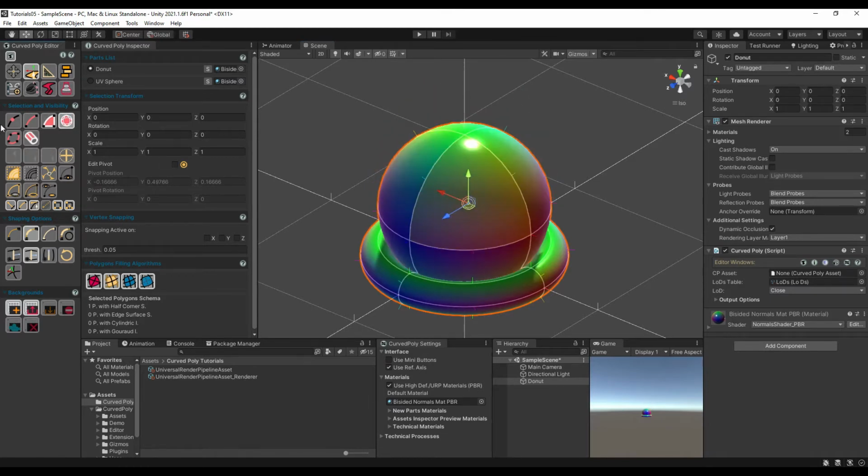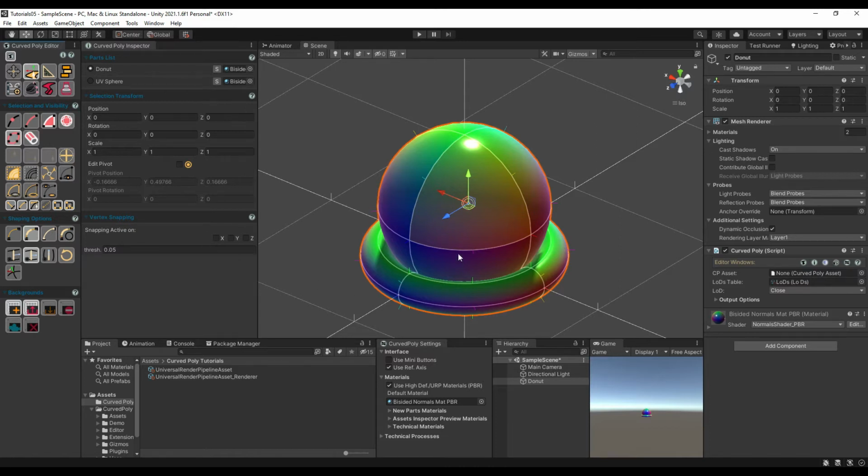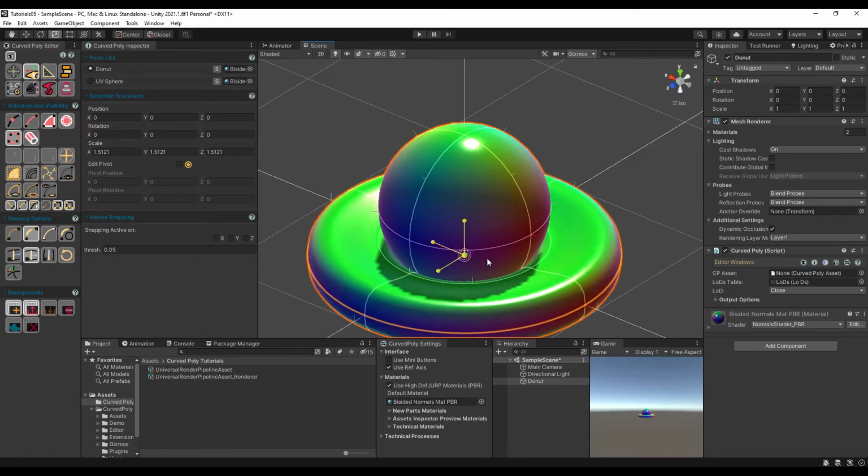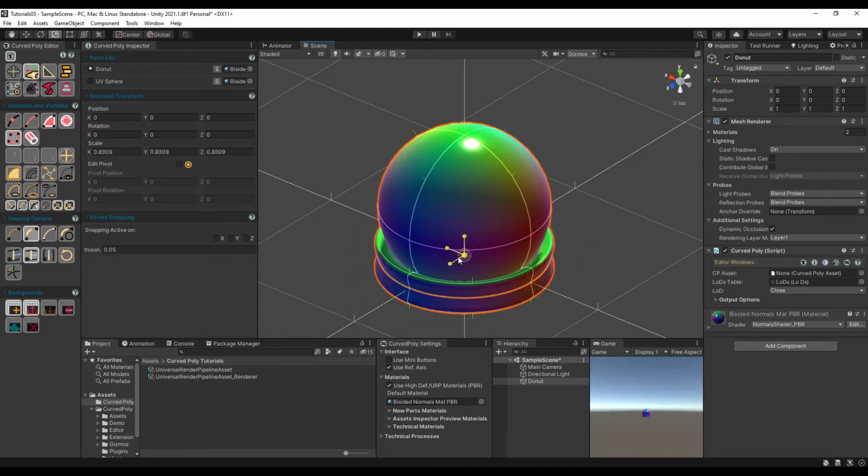A loop is a loop of chained edges. In order to pick a loop, we need to click on one of its edges. The condition for 2 edges being in chain is that they meet at the same vertex, and that they are almost aligned on that vertex. For example, loop is useful to shape at once loops of edges on cylinders, or on other similar primitives. Depending on the edge you start with, the loop may be closed or open.